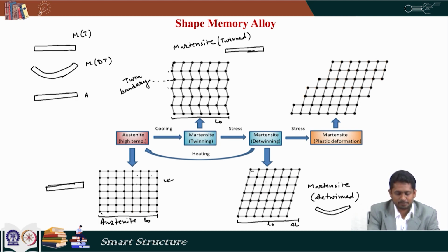So, although by heat actuation it regains its original shape, it does not go to the twinned martensite phase, because it is at the higher temperature, and at the higher temperature the stable phase is the austenite phase, but macroscopically they look the same. So, we have twinned martensite, detwinned martensite, and then we apply heat to it and it becomes austenite.